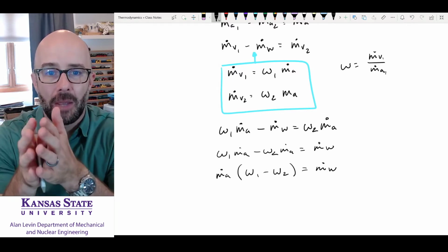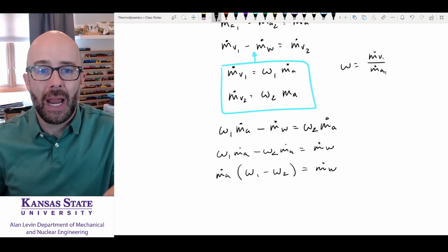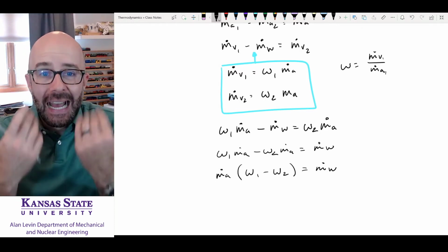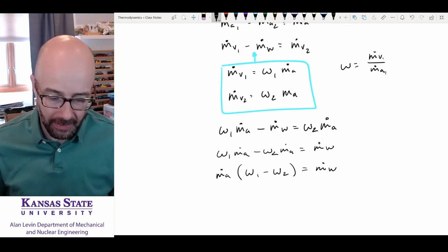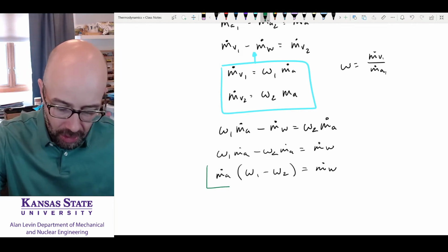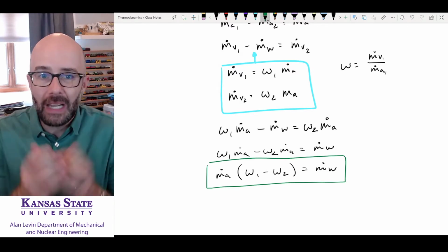There's going to be a difference in the humidity ratio. If I take that times how much dry air is going through that, I find out how much liquid water has dripped out of that system. So that makes sense, and this will be a very useful equation. I want to put things in terms of omega if I can. Now let's go look at our first law.